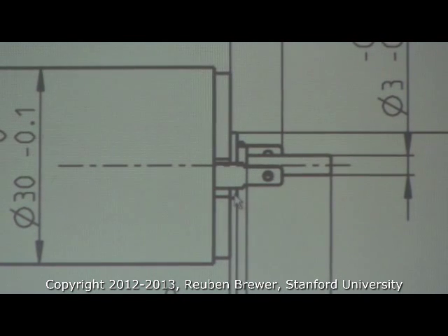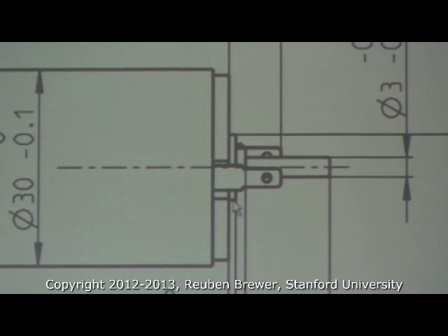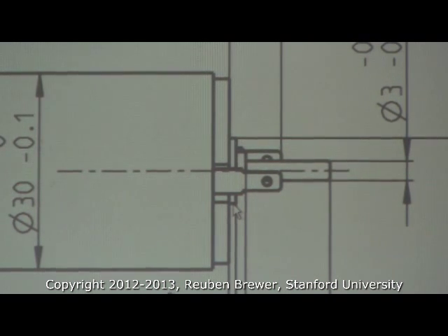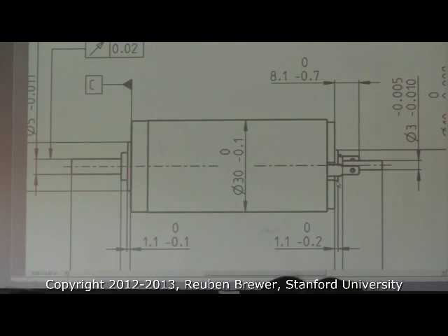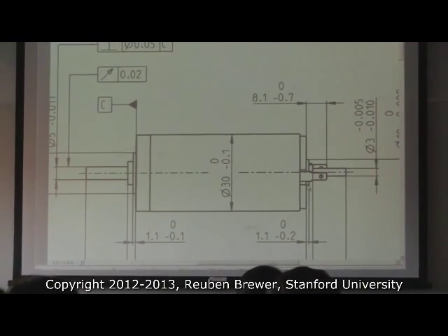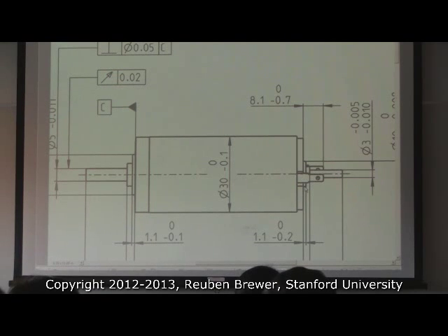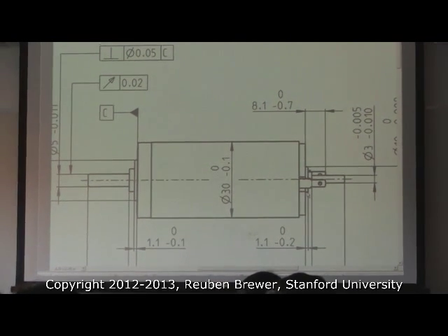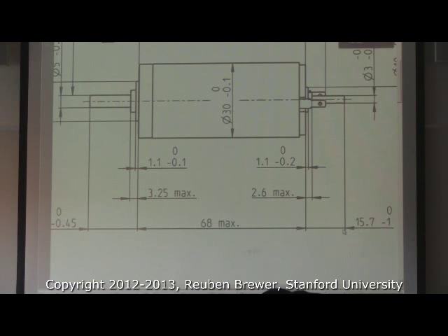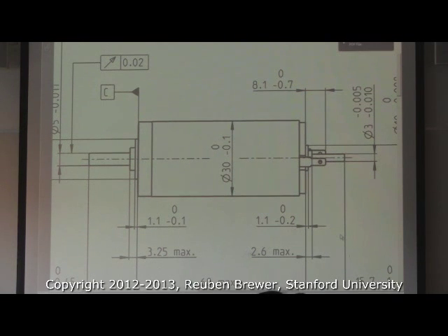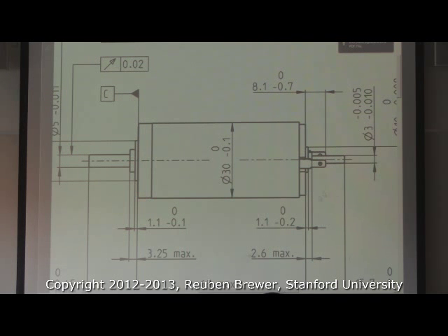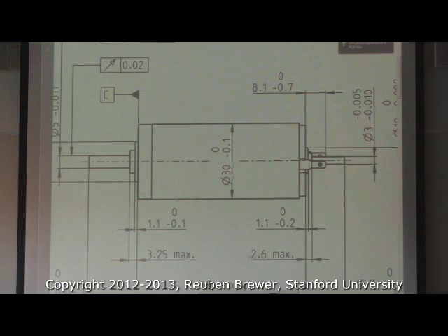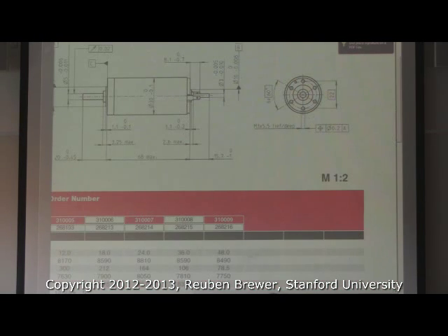The exact same thing. Now again, remember, cheap motors often don't have back shafts, or they often have back shafts that are so tiny you can't fit an encoder on them. Some Maxon motors, and I don't know why, have really short shafts. Make sure that you're going from the spec sheet so that you see what this distance is, 15.7 millimeters, and in your CAD put the encoder and the adapter plate on first before you order the motor to make sure you can do it. And you're going to be using this little hub here, front and back, to line everything up.